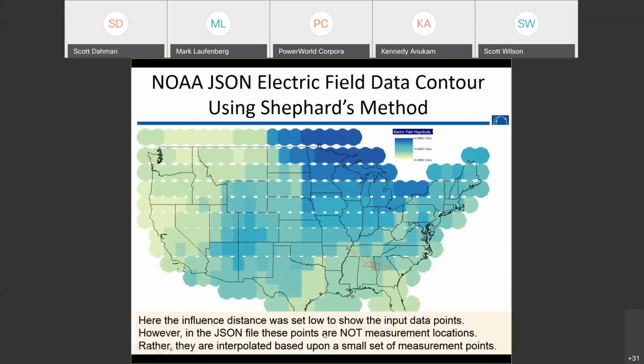And then just a little bit on the contouring. We mentioned that interpolating the E field between points is now using the Delaunay triangulation method. Contouring gives you an option that, previously in Simulator for the last 25 years or however long it's been, we've used Shepard's method for contouring. And this is an example of how that looks. The influence region on this screenshot is a little bit smaller, so there's some dead band in between there. This looks like it's about a 2x2 grid.